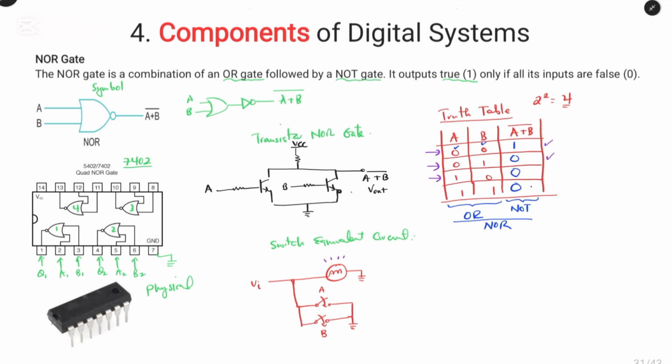The third combination, we have 5 volts at input A and 0 volts at input B. Now all the current will pass through this transistor and towards the ground. No current will flow to the voltage out to drive the load. Therefore, the output will be low and having a binary state of 0, and this can also be proved from the truth table. Similarly, we will now have current flow through switch A. No current will pass through the lamp. Now the lamp is off.